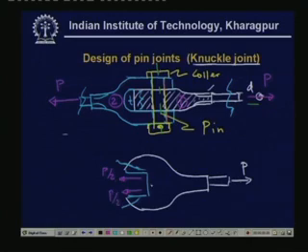So then the material fails under shear. Because the force is a shear force, we'll have to calculate the shear stress. Then the next step is to calculate the shear stress, and this shear stress will be equal to P by 2 divided by, this is the average shear stress, divided by this length,